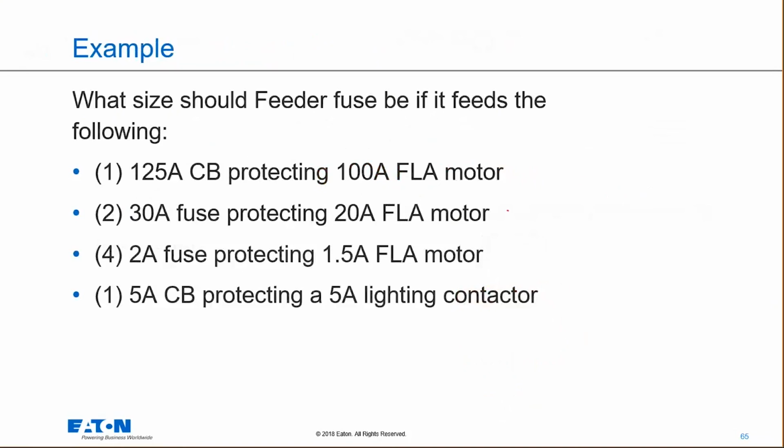So if we look at how to size this, I'm going to take you through a quick little example. What size should the feeder fuse be if it feeds the following? I've got a 125 amp circuit breaker protecting a 100 amp motor. I've got two 30 amp fuses protecting a 20 amp motor. I've got four 2 amp fuses protecting a 1.5 amp motor. And then finally a 5 amp circuit breaker protecting a 5 amp lighting contactor.